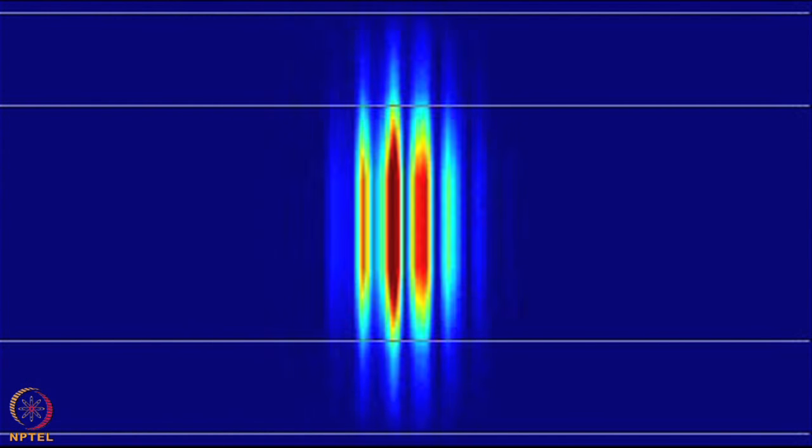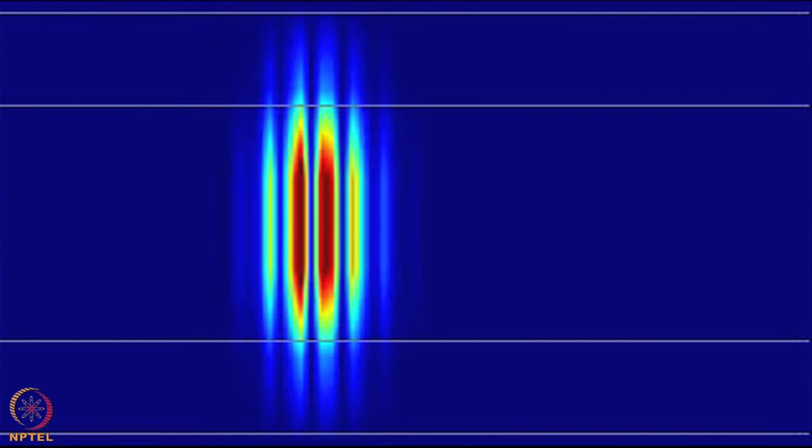So in the case of lambda by 3, there are not enough grid points to sample the wave, so it's not really simulating the real physics. Whereas in lambda by 5, we have enough points per lambda, so we're able to see the wave actually propagating. And obviously there are some errors which might be reduced further. So this is lambda by 10. So can you show the lambda by 10? We can see a clear mode. So you see a clear propagating mode inside.